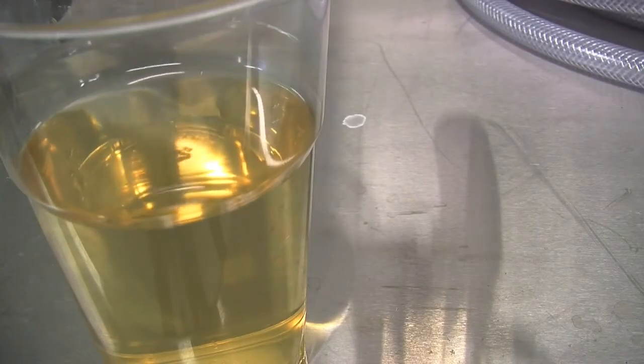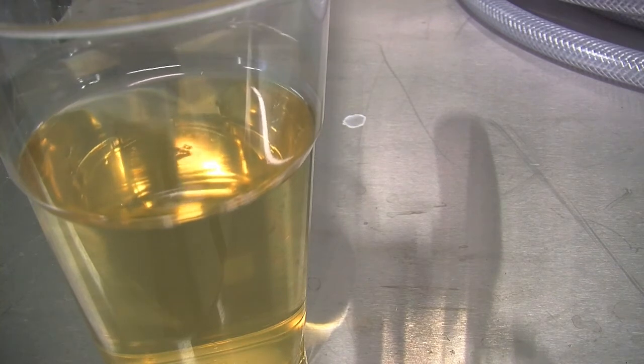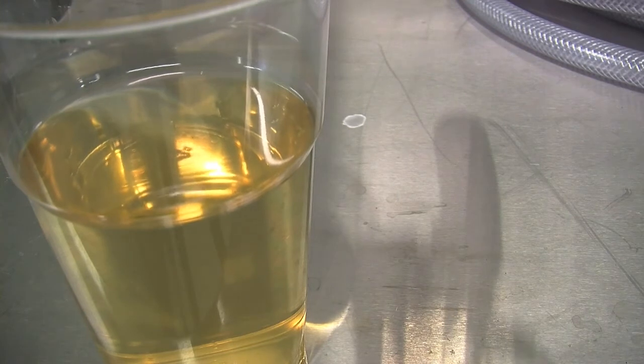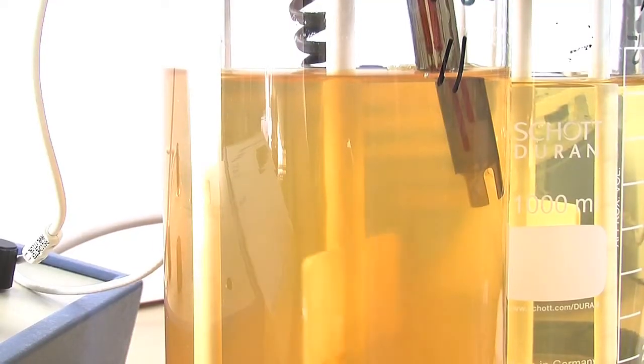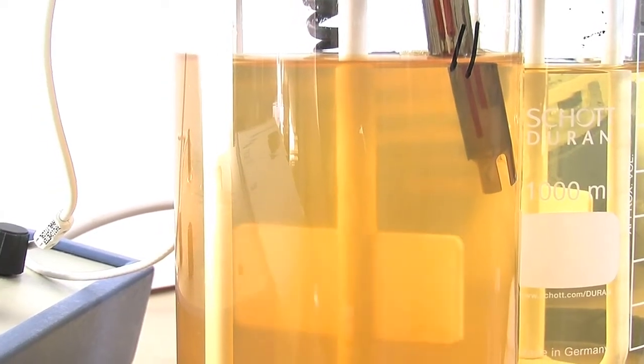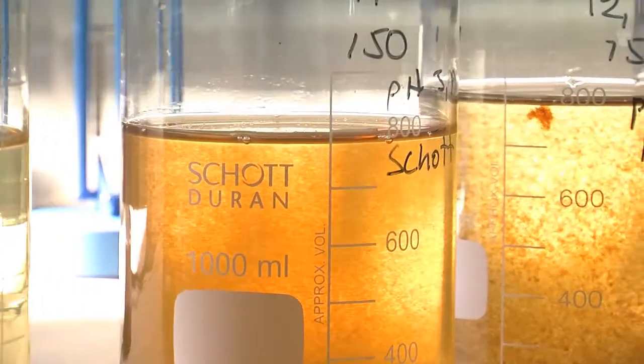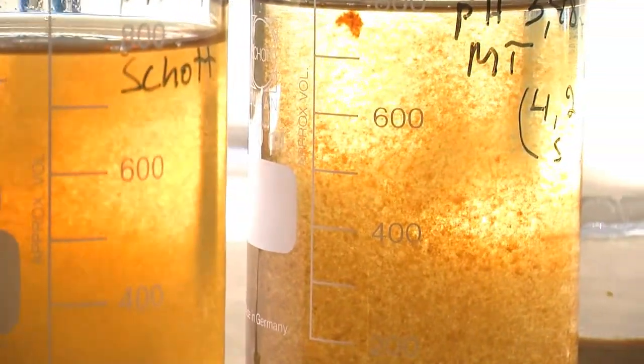The color and turbidity of river water is caused mainly by colloidal-sized clay particles and humic substances. Although the density of these materials is higher than water, the particles do not sediment due to the small particle size. Chemical precipitation using iron salts encourages humus and particles to coagulate, forming bigger flocks that can be separated out.